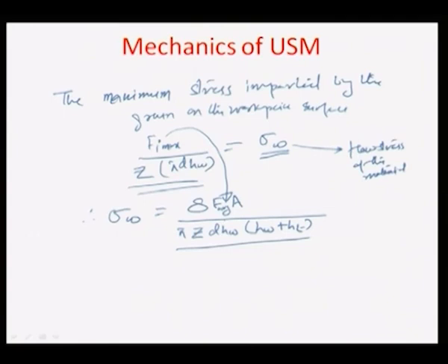And we can always say that if h be the indentation depth, this h can be inversely proportional to the flow stress of the material, meaning thereby that if a material has a higher flow stress, for a certain force level it would have a lower depth of indentation and vice versa.